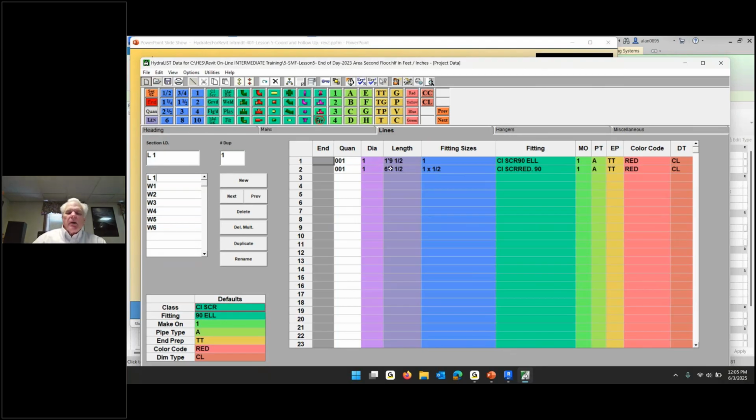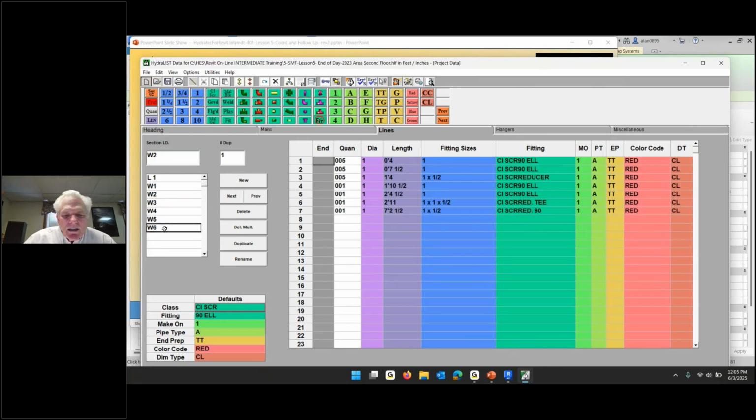I think this is the one that goes up and over into that communications room. It was the threaded pipe that we saw. W1 is just short pipes. I'm thinking that's the return bends, the arm overs, and the drops. W2 probably more return bends and drops. W6 is return bends and drops, but it's got this reducing T and this reducing elbow. I'm saying that's the threaded pipe coming off of that north branch line.